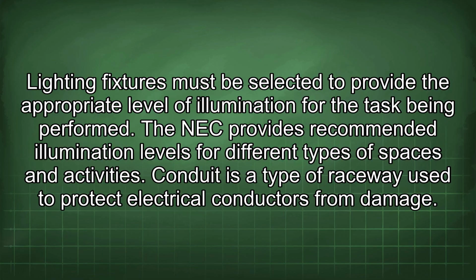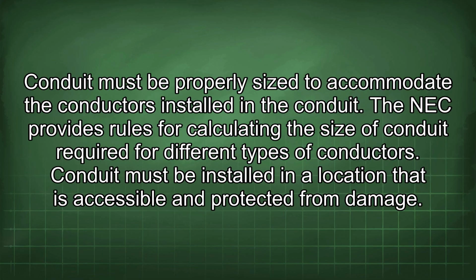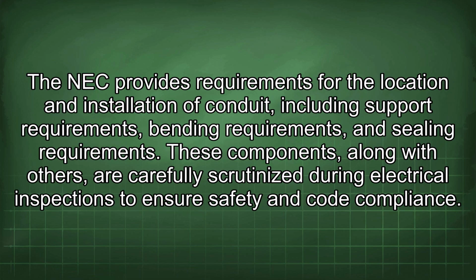Conduit is a type of raceway used to protect electrical conductors from damage. Conduit must be properly sized to accommodate the conductors installed in the conduit. The NEC provides rules for calculating the size of conduit required for different types of conductors. Conduit must be installed in a location that is accessible and protected from damage. The NEC provides requirements for the location and installation of conduit, including support requirements, bending requirements, and sealing requirements. These components, along with others, are carefully scrutinized during electrical inspections to ensure safety and code compliance.